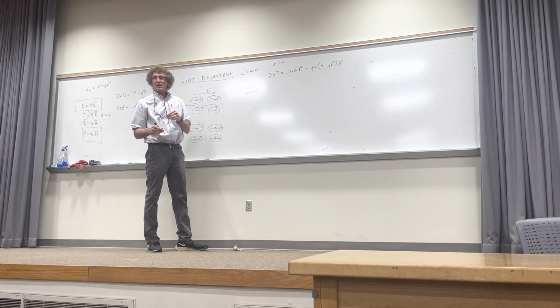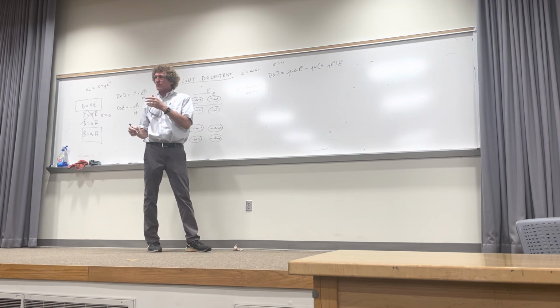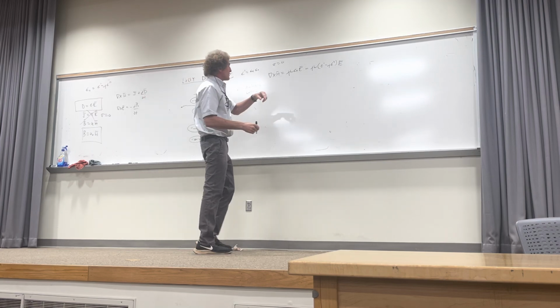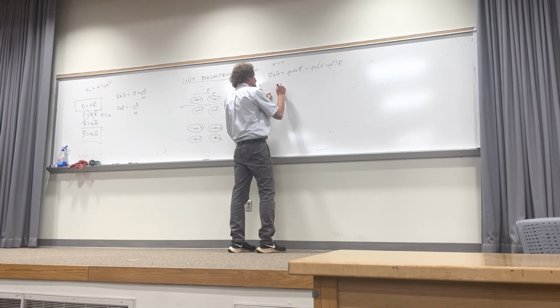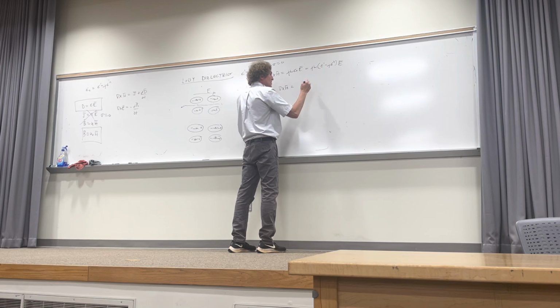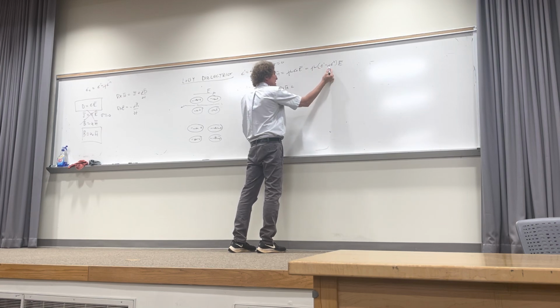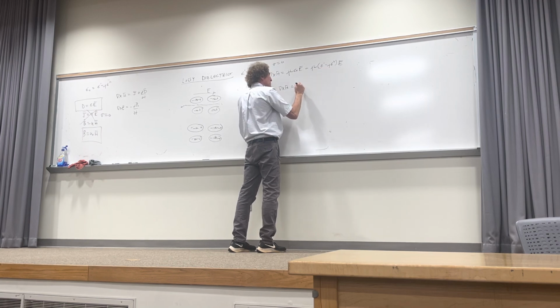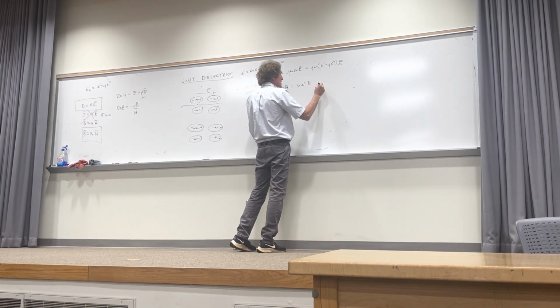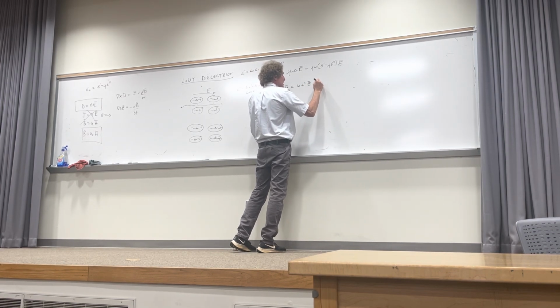I'm going to keep talking about this in a way I hope will really show you why this is important. If you go here and you take the next step, that means curl of H is equal to, well, you're going to have j omega times, j is, well, times minus j. j times j is minus 1, times the minus is plus. So I get omega epsilon double prime E right here. And then I get plus j omega epsilon prime E.